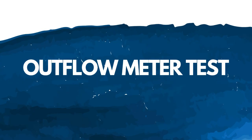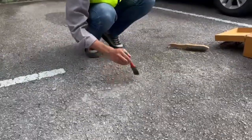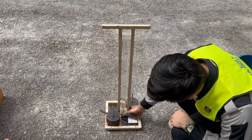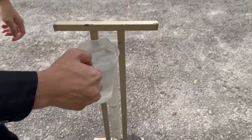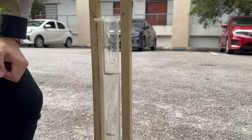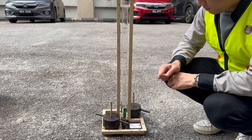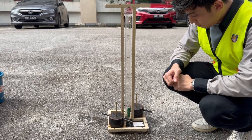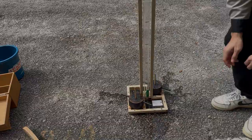Next, for the outflow meter test, clean the spot from debris with a brush. Place the outflow apparatus on the spot and place weight on it. Stop the outflow in place. Fill the outflow meter test apparatus until it reaches 400 ml. Pull the stopper out and start timing the rate of water flowing until it reaches the lower graduated mark. Record the data obtained into the table. Repeat the steps for medium rough surface and smooth surface.